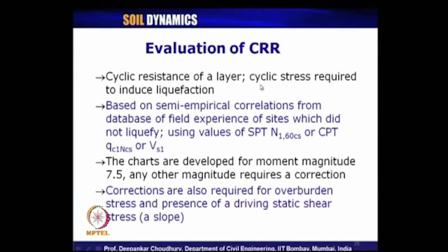So, that is why Seed and Idriss, when in 1971 they proposed the equation for factor of safety, they gave the equation CSR at 7.5 by CSR, meaning they have used both CSR. One is required to induce liquefaction at moment magnitude 7.5, to how much cyclic stress ratio is actually getting developed for a particular earthquake.